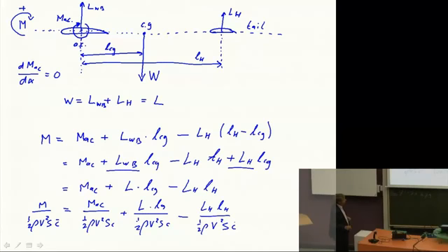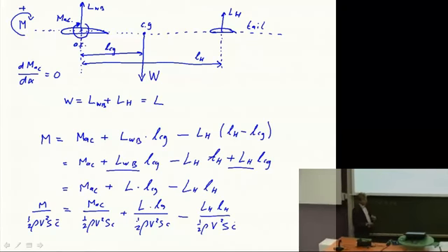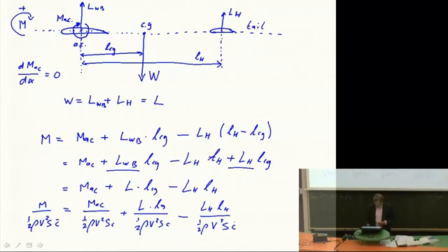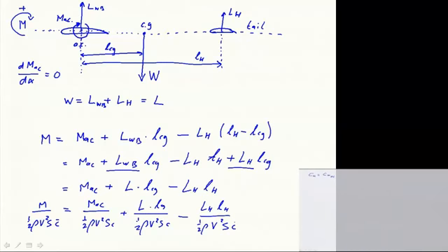And here, that doesn't really work that well, because this is the area of the wing, and if we use the Cl of the airfoil, we should use the surface of the airfoil. So if we want to replace this by CLH, we still have to multiply it by SH and divide it by S. In other words, if we write this as a dimensionless equation, you can see it in the handout as well, we get Cm is Cm in the aerodynamic center plus Cl times LCG divided by the average chord minus CLH times LH divided by the chord, but also the two different surfaces. So CLH times LH divided by S is basically what we had at the previous slide, times LH over C.